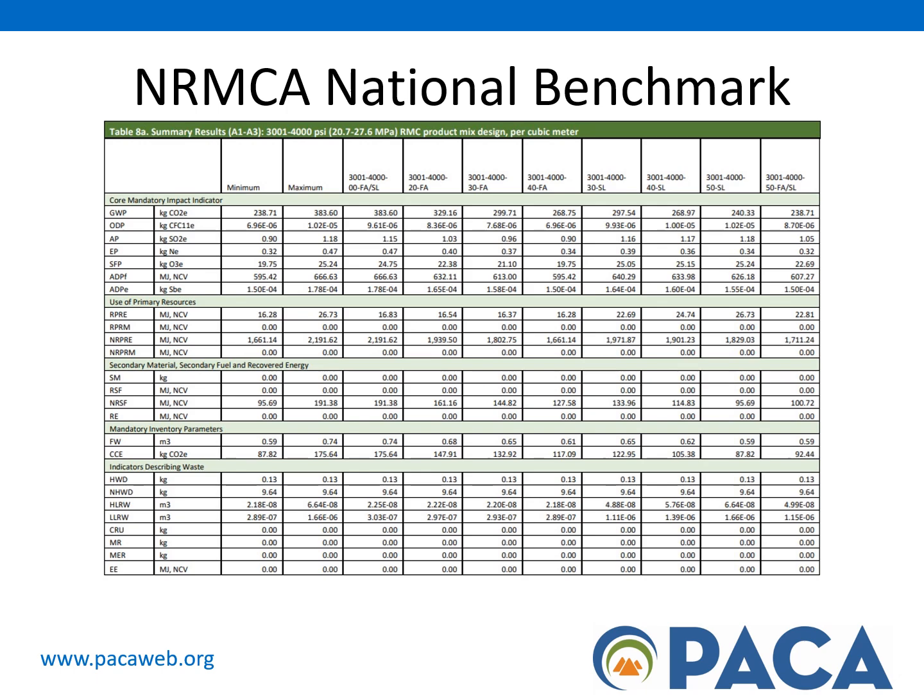To read the chart, we see the vertical axis represents the level of environmental impact, kilograms of CO2 equivalent for the global warming potential as an example, while the horizontal axis lists the different concrete mix designs or classes. By looking at the benchmark lines, we see the national average lines for each impact category against which specific mixes can be compared. The basic use of this chart is for comparison, goal setting, and reporting.